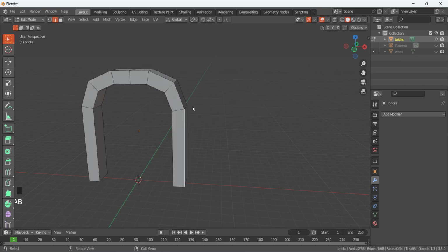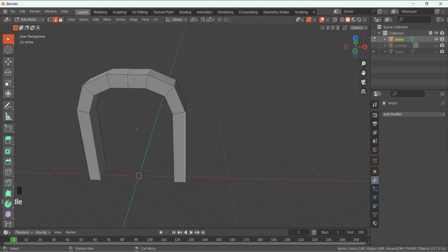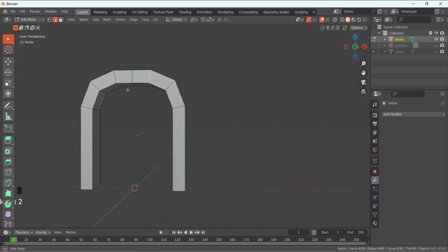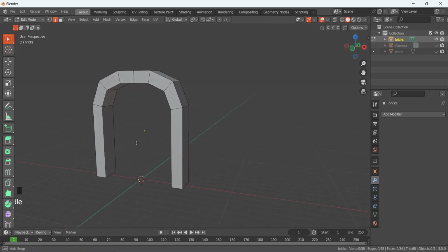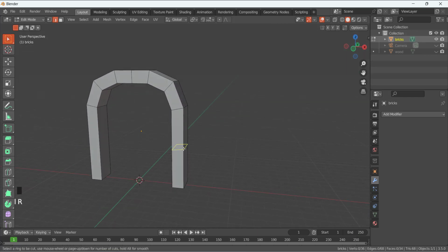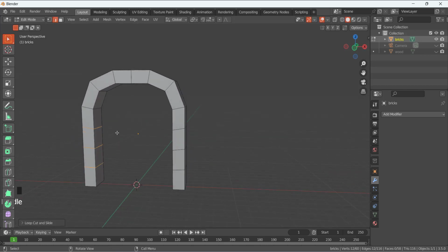Okay, go to the edit mode, and here I have to select all of these edges. So basically press Alt, and if you click here, you can see all of these edge loops are selected, and then press Shift and Alt and select all of these edges, and not this one in the middle, like that. The other thing is that you can also press Control R and add three loops here. So we just added this geometry by using Control R.